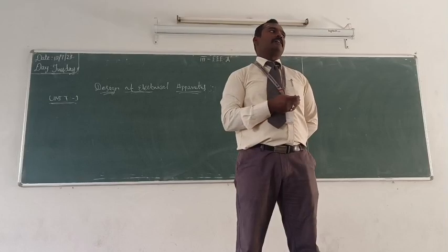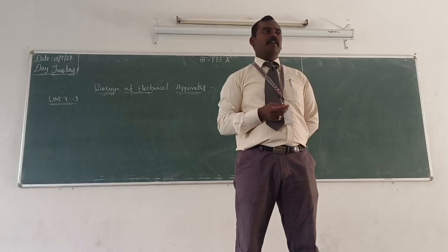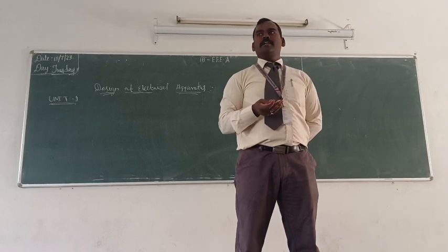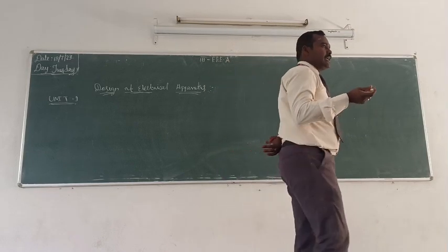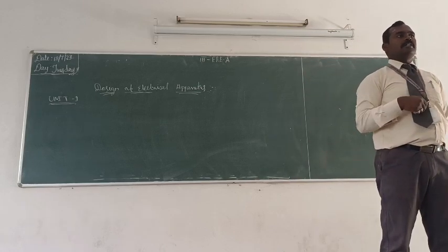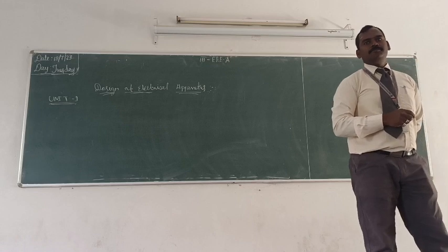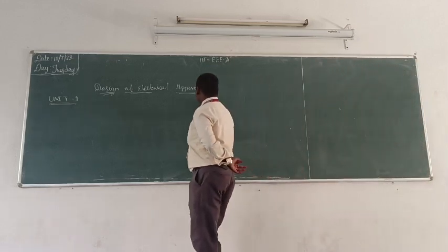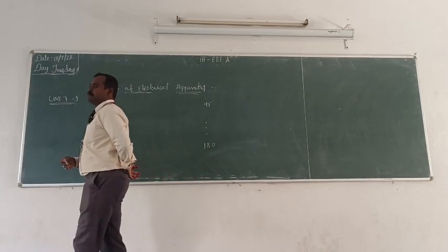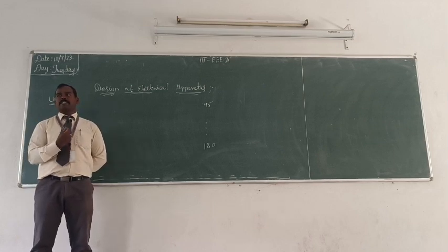So if you consider conducting materials, there are two different types: high resistivity conducting material and high conductivity conducting material. Again, the superconducting material and the normal conducting material like copper and aluminum, which we are using in the major conducting parts of the machines, right? Then the insulation material we discussed based on the various operating temperatures, starting from 95 up to 180 degrees Celsius and above. Based on the operating temperature, we can select the most appropriate type of insulating material.